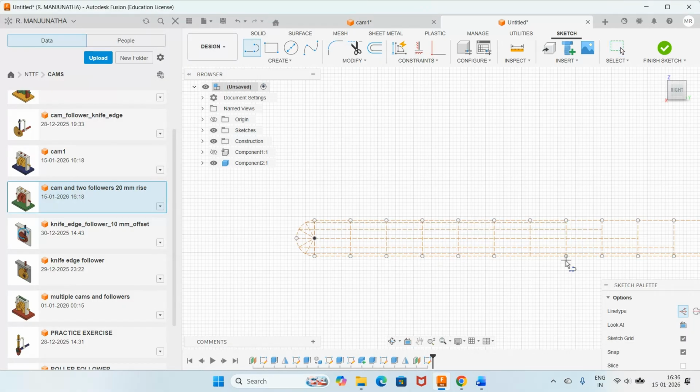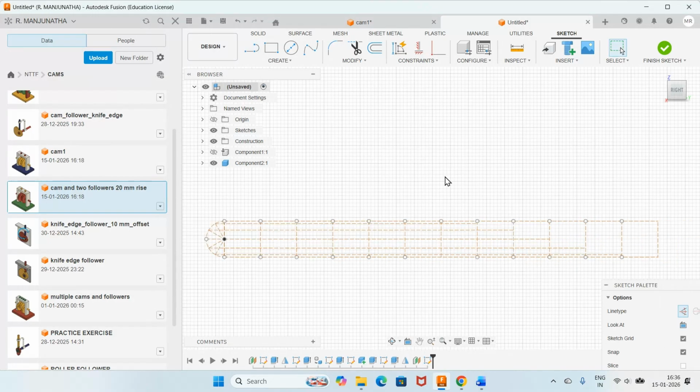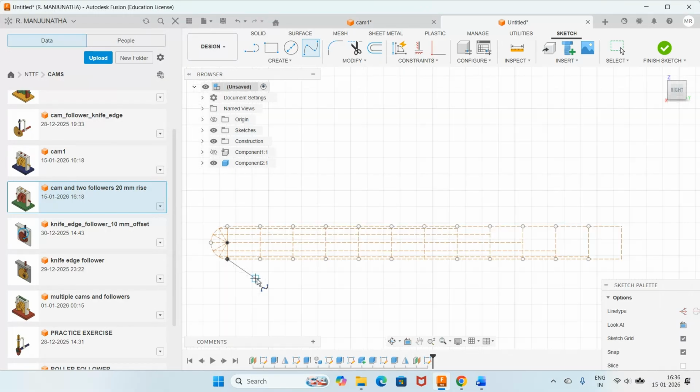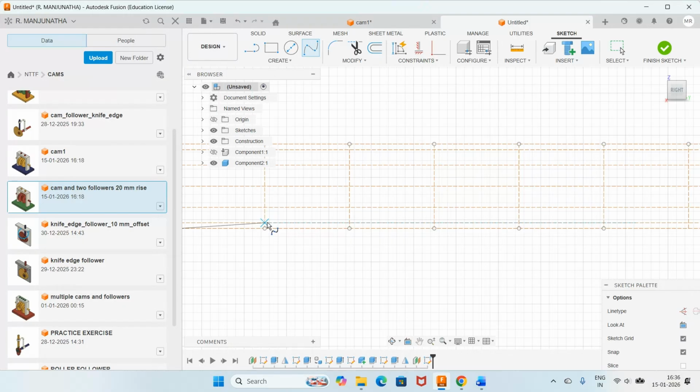Once you do that, now I want to draw a curve. Go to fit spline and remove construction and I want to draw the actual line now. You just take the endpoint. Similarly, you come down to the intersection of this, to the intersection of this, to the intersection. Okay. Take this intersection and take this intersection to this endpoint.